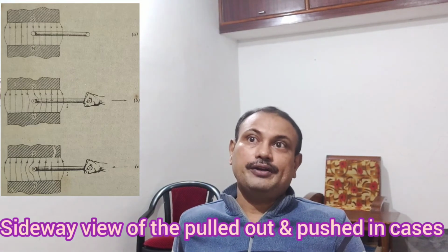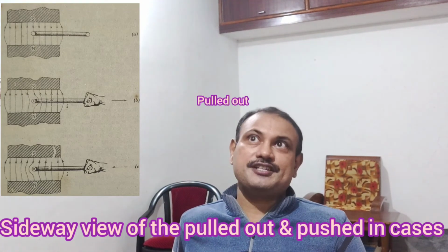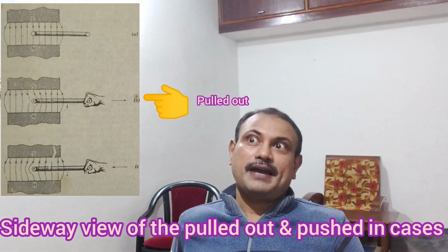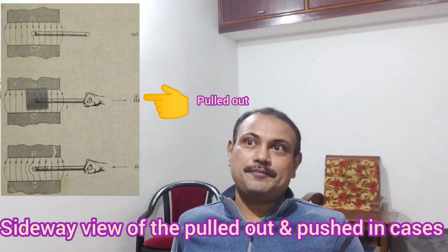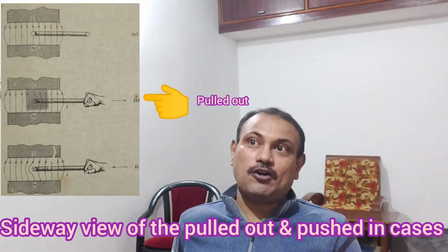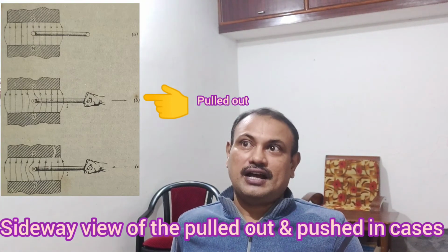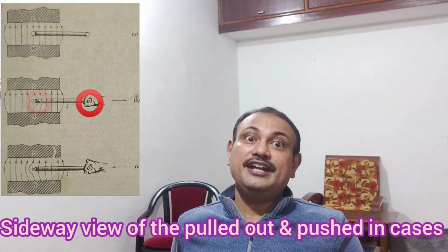And in the second figure, when the conductor is pulled out, as in our case of discussion, when we take away the conducting loop, the magnetic lines of force are bent, as shown in the picture. That means it is opposing the motion and the agent is experiencing an opposition. Why? It is because an additional magnetic field is being created, as we have seen in our case. And the same has been given in a dot and cross manner at the ends of the conductors, if you carefully mark.